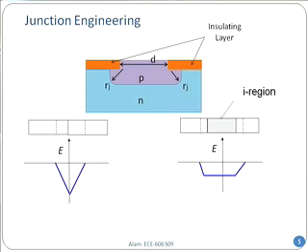And in fact, this is what you will hear as we go on, the term called lightly doped drain. This was a huge problem in the 1980s for MOSFET design, because MOSFETs were failing by hot electron injection, and one person essentially came up with the idea that you just put a lightly doped region in between the heavily doped regions. I will come back to this point again.